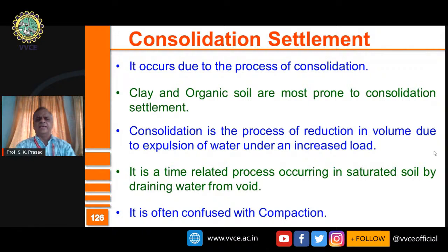Mainly it is the clay soil, and consolidation is a major culprit for a huge amount of settlement. Let us see how you can compute this and how you can reduce the consolidation settlement to the best extent. It occurs due to the process of consolidation. Clay and organic soils are the most prone to consolidation settlement.